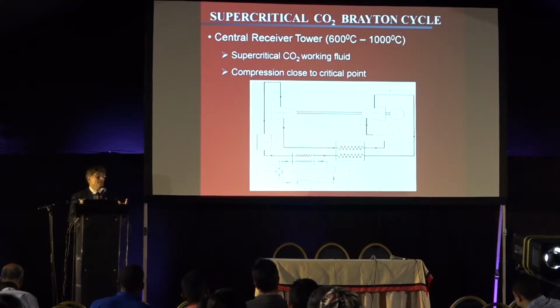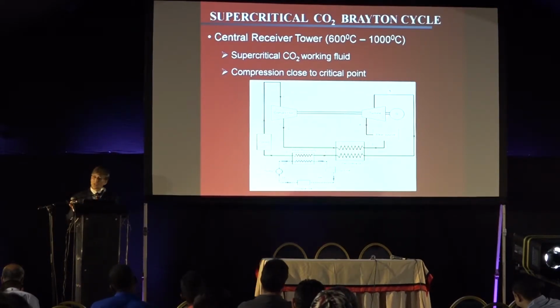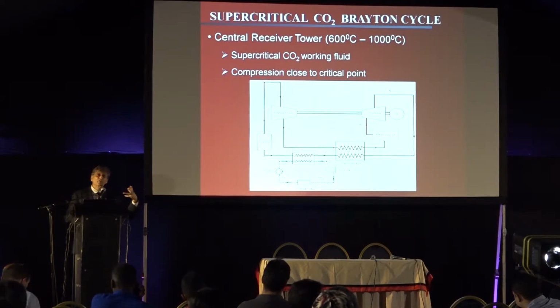So then you say, well, if you compress a gas, that requires a lot of energy. But in this case, when you get close to the critical point, still remaining in the supercritical range, the density of carbon dioxide is like the density of a liquid. And therefore, it does not require as much work to compress it as a gas would. So it gives you an advantage of being a gas, but at the same time, advantage of what a liquid would give you in terms of increasing the pressure.